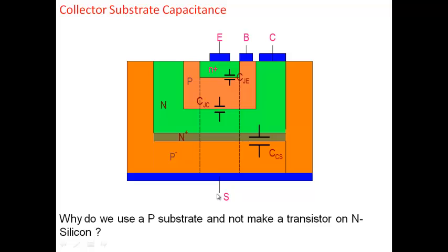Right? And so a bipolar transistor, if you look at it from this picture, is not just a three-terminal device: emitter, base, and collector. The emitter, base, and collector are made on top of a substrate. And the substrate is also another terminal, right? And the substrate is usually kept at a large negative voltage. Why do I do that? Large negative voltage and fixed, because you will see in a minute.